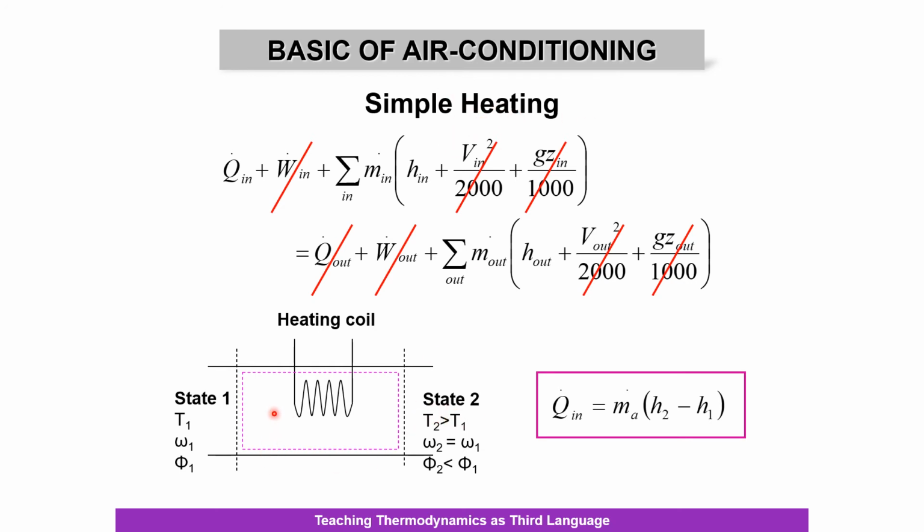But because you are not adding or removing any moisture, in other words, there is no humidification or dehumidification process, your omega remains the same, right? But since it involves a change in temperature from state 1 to state 2, your relative humidity will change as shown here, right?